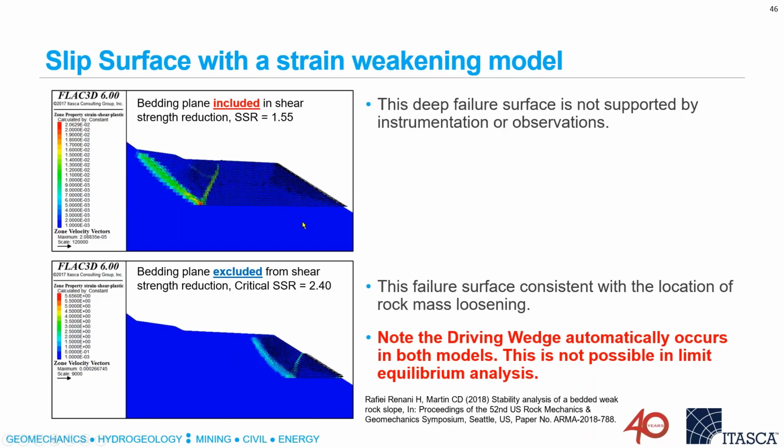And the second point is that with the shear strength reduction method and numerical methods, we can choose to not reduce properties of various components if we want to. Maybe we think that they are already at their residual strength and can't get any lower, or we may just want to find out a partial safety factor due to other components, and this is all possible with numerical methods.